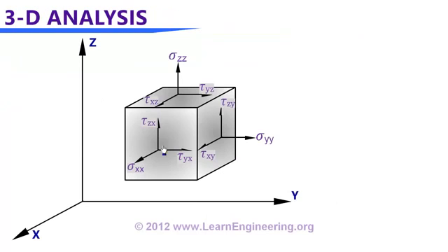Here it is. In 2D cases we are doing stress analysis on a square, but in the 3D case instead of a square it will be a cube. And these are stress values at the boundary of this object. It has 3 normal stress and 6 shear stress components. In the 2D problem we deduced a principal square inside the object, a square comprising of principal planes. Similarly here we can deduce a principal cube comprising of principal planes inside the object. It will look something like this.